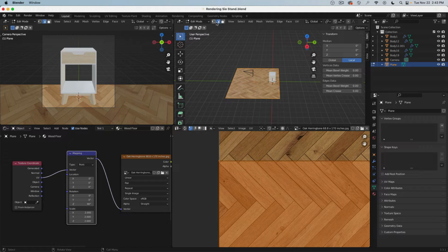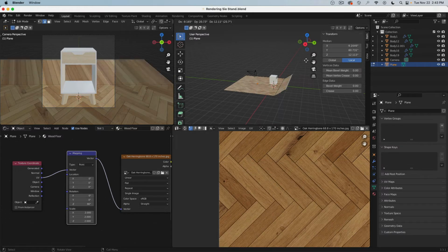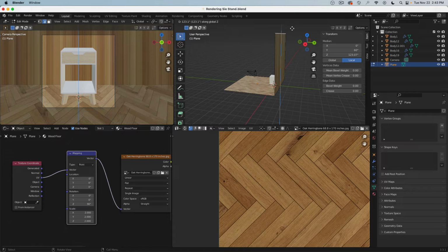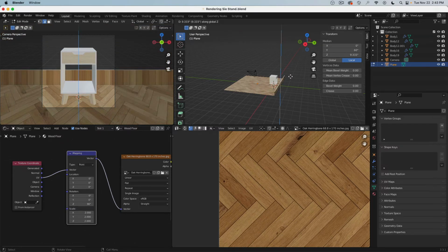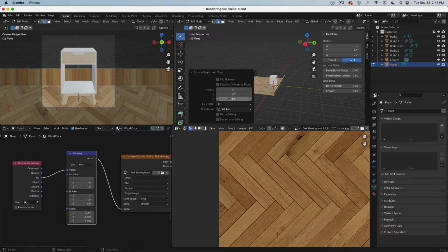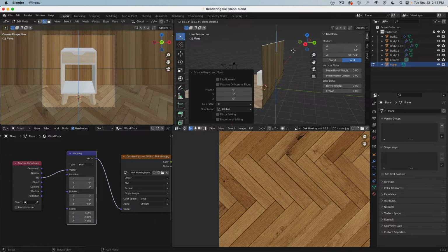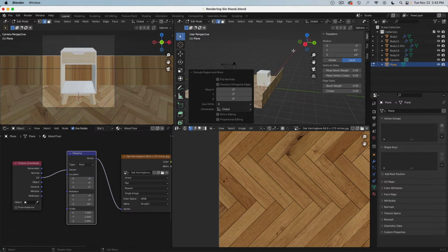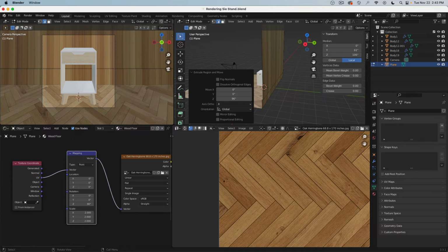Let's go to Edit, Edge Select. Then I can press E and Z and drag this one. Maybe how far do we drag this up? 10 inches and enter. Also here you see I move this up 10 inches. I'm in inches. Then I press E and Y and 1, so 1 inch back, and E and Z, let's say 8 feet. See, 8 feet, when you work in inches, it doesn't understand, but we can type in 8 feet this way.